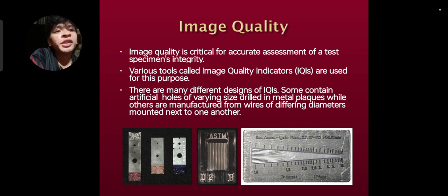Actually, there are different kinds of IQI designs. Some contain artificial holes of varying sizes drilled in metal strips, while others are manufactured from wires of different diameters mounted next to one another. What you can see in the pictures is a sample of the image quality derived from the testing.